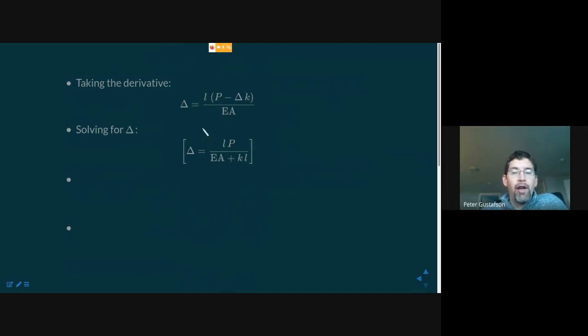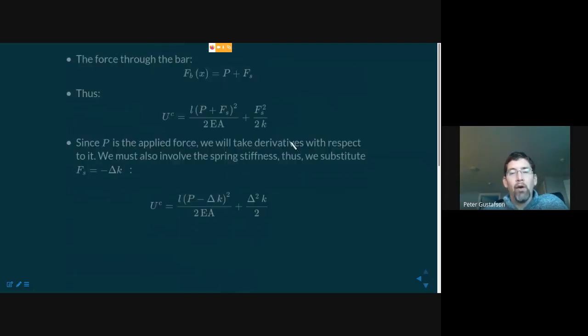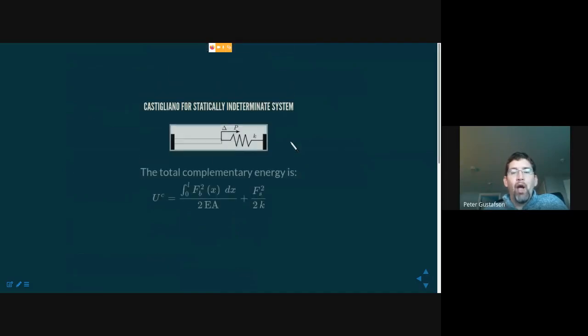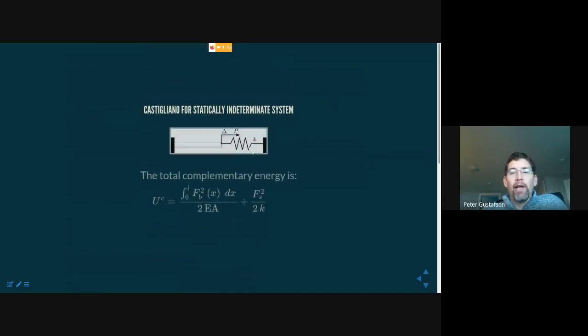There's another sanity check that I would suggest, and we kind of alluded to it already. If I go back to this diagram, let's do a quick calculation of what happens if we took the spring away, meaning we set its stiffness to 0. So if K is equal to 0, do we recover a reasonable calculation for displacement?